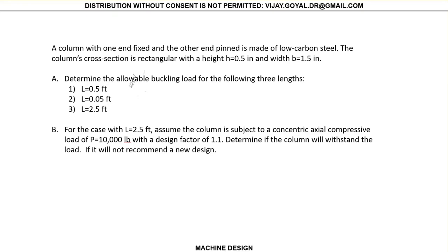What we have is the problem set has one end fixed and the other end pinned. Okay, those two are very important points, because it's going to depend on the end fixity of your problem. So it's saying one end is fixed, and one end is pinned. Now, there are many ways you can put a pin. So this end is pinned. You used to put a roller, but there are other ways to do that. I will talk about that in a moment.